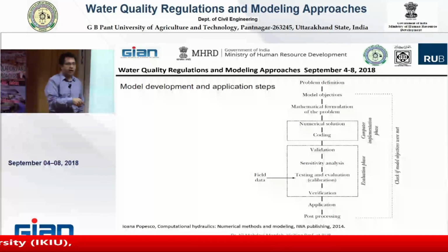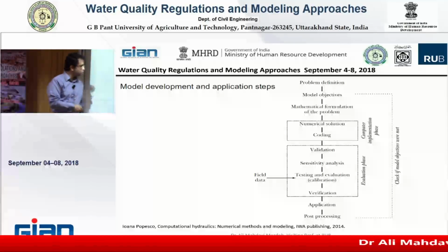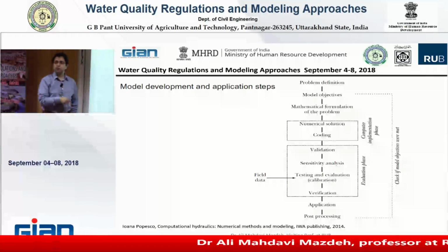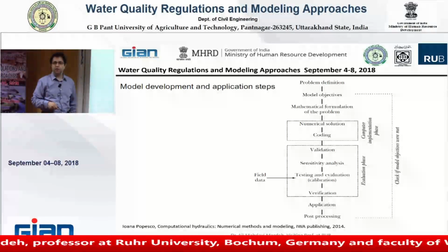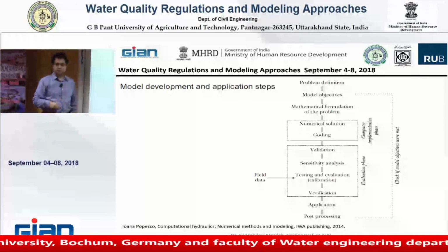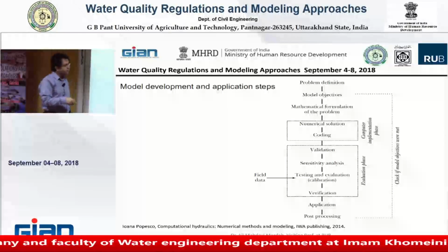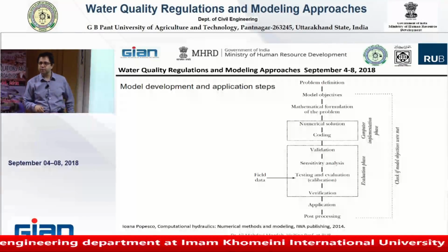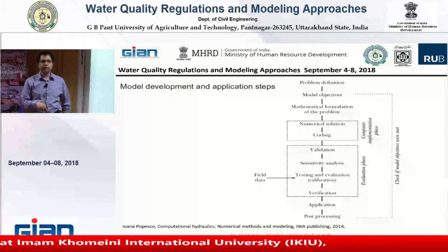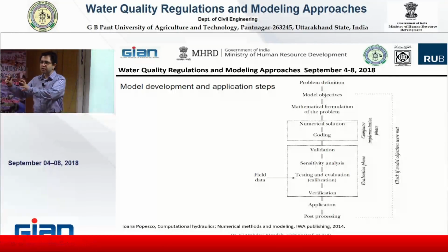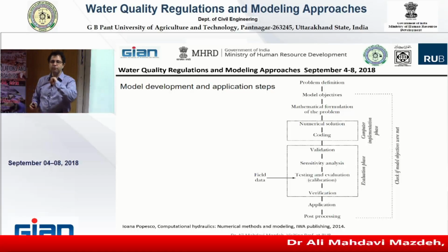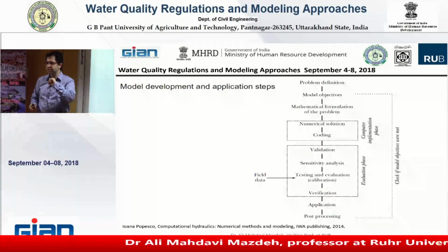Here we need this. At first, you must calibrate this with field data. You must have some data, and you calibrate your formula, and you find this C. For this formula, the scientists did it for us several times. Because of that, you have a lot of curves that show you, based on the characteristics of the weir, what the number of C is.